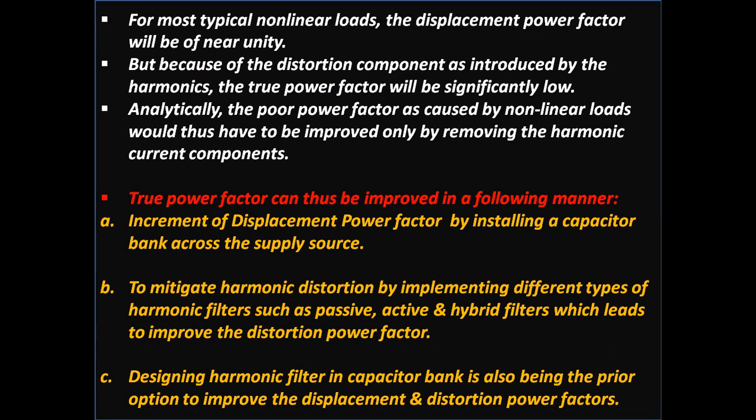Analytically, the poor power factor caused by nonlinear loads would have to be improved only by removing the harmonic current components. True power factor can thus be improved in the following manner: a, increment of displacement power factor by installing a capacitor bank across the supply source.